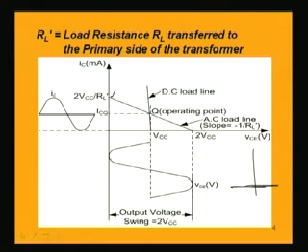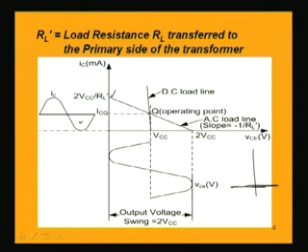and then it will be again increasing. In this half cycle, when the AC collector current goes to the negative half, the collector to emitter voltage will increase beyond VCC, and the increment will be to this point, the maximum point on the load line, which has the voltage of 2 times VCC. Now, why does this maximum voltage between collector and emitter become 2 times VCC?